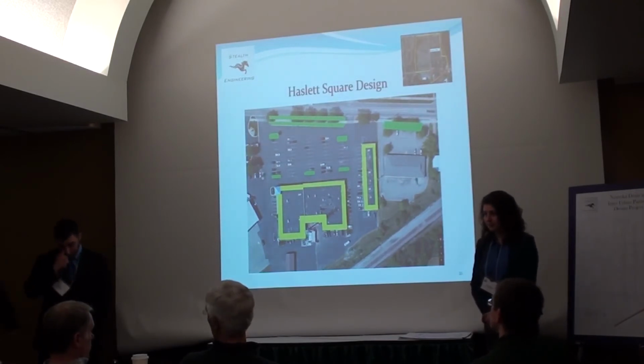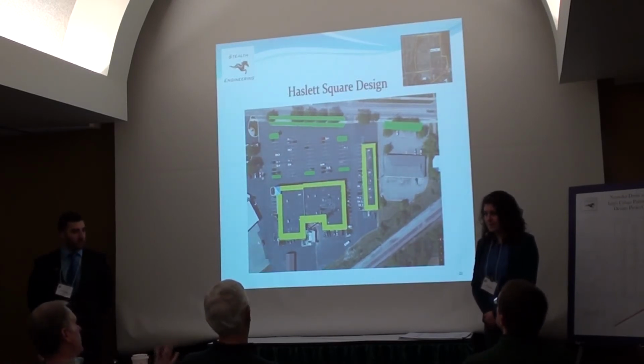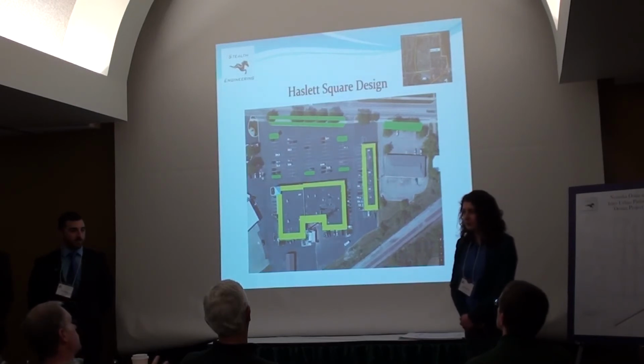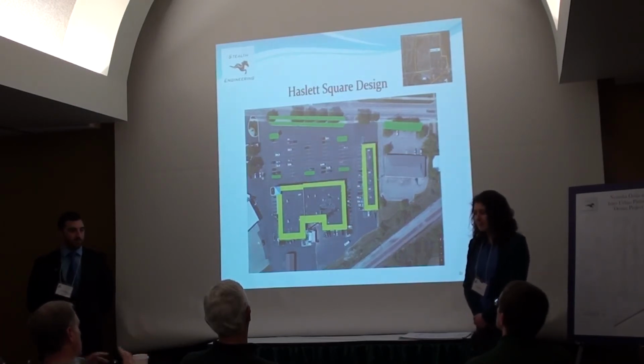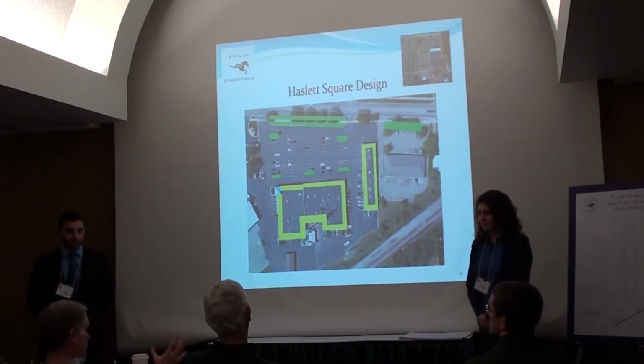There's a couple of things I'm thinking of. One is, what kind of structure can you have up there? How are you going to hold that water? What's the bathtub going to look like? And what kind of weights are you looking at? Consider all the roofs that collapse because of snow loads. Now this roof may already have been designed. The roof obviously had to meet building code. It probably does, I'm sure. Are you imposing more load than that snow load might have? Are you going to have issues with your structure?